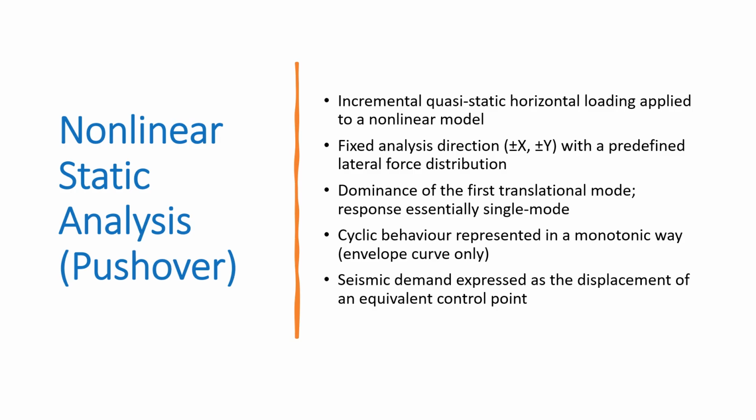In this case, we consider different analysis directions with a predefined load pattern, implying that there is a dominant translational mode, which is represented by this force distribution, and the response is essentially a single-mode one.